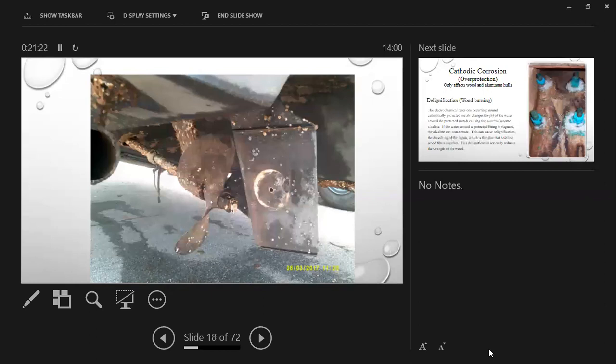But you've got a stainless steel shaft, probably a manganese bronze propeller, a bronze rudder. You've got all the makings of an electrochemical cell. You've got anodes, cathodes, you've got the electrolyte as the salt water it's sitting in, and all this stuff is probably bonded together. So you've got a real good galvanic cell there.